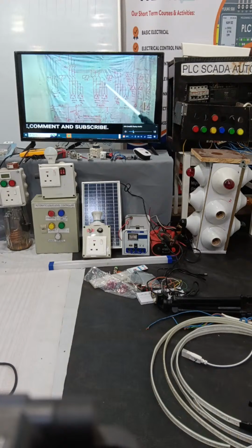The second set is K1.2, and it is feeding 1C3, 1C4, 50 kVA, 25 kVA each. The third set is K1.3, it is feeding 12.5 kVA capacitor banks for each contactor. And the designation is 1C5, 1C6.